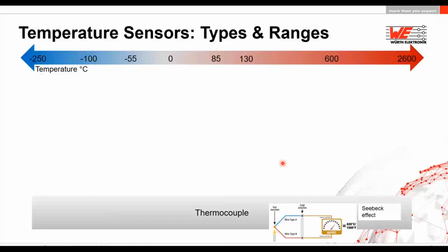the thermal conductivity is different, so that they produce some millivolt outputs that can be directly linked to the temperature. Basically, the thermocouple uses a reference temperature as a cold junction, and the hot junction is the temperature where you measure with respect to the temperature of the cold junction. On the other hand, these kinds of sensors are highly nonlinear. Also, they are not stable and the accuracy is not so good.